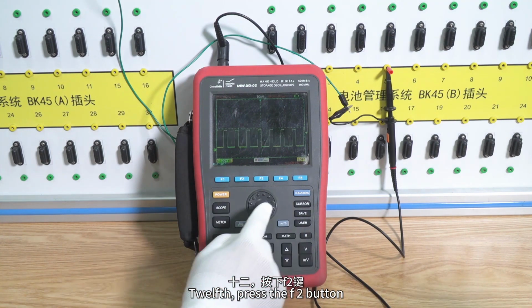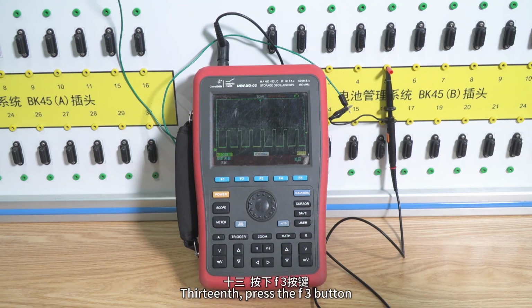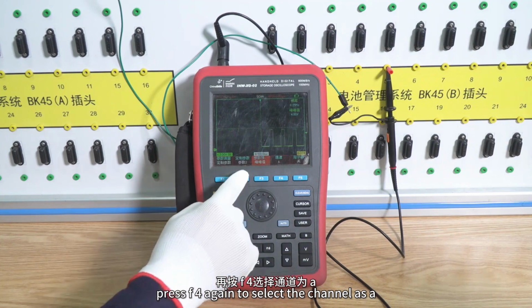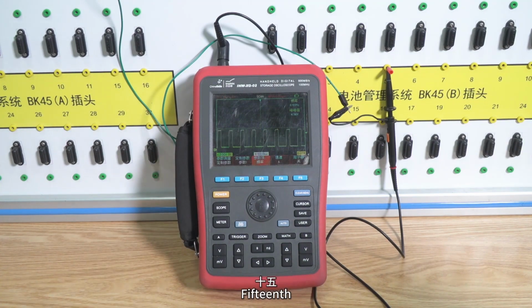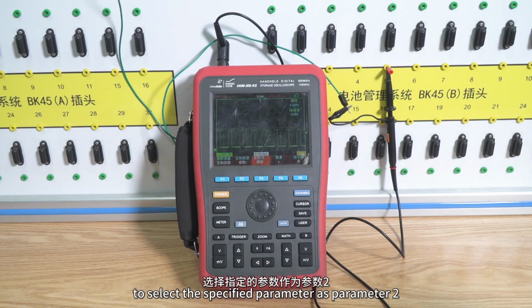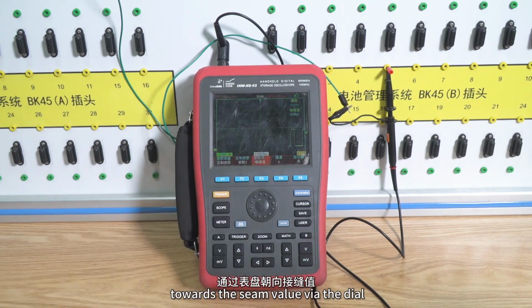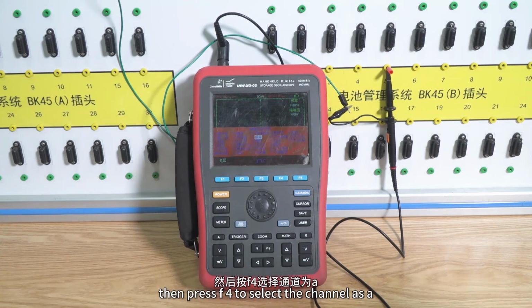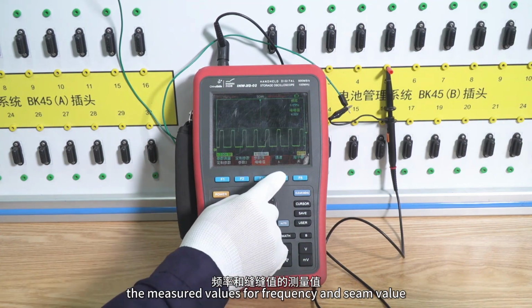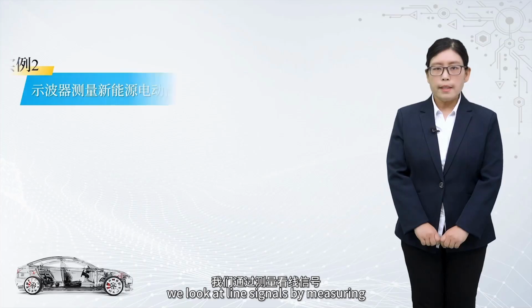12th, press the F2 button to select the specified parameter as parameter 1. 13th, press the F3 button and use the dial to select the parameter to frequency. 14th, press the F4 again to select the channel as A. 15th, press the F2 button again to select the specified parameter as parameter 2. 16th, press the F3 button and select the parameter to be the peak value via the dial. Then press F4 to select the channel as A. At this point, we can see that the measured values for frequency and peak value are shown in the upper right of the display.